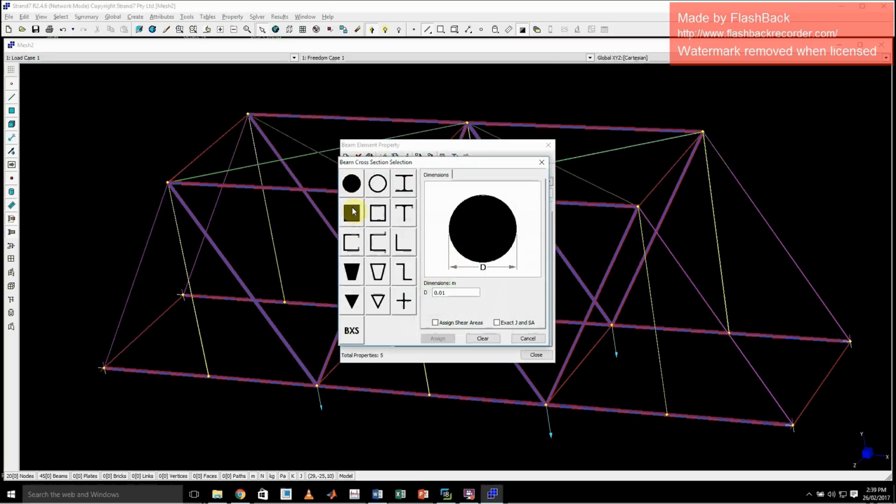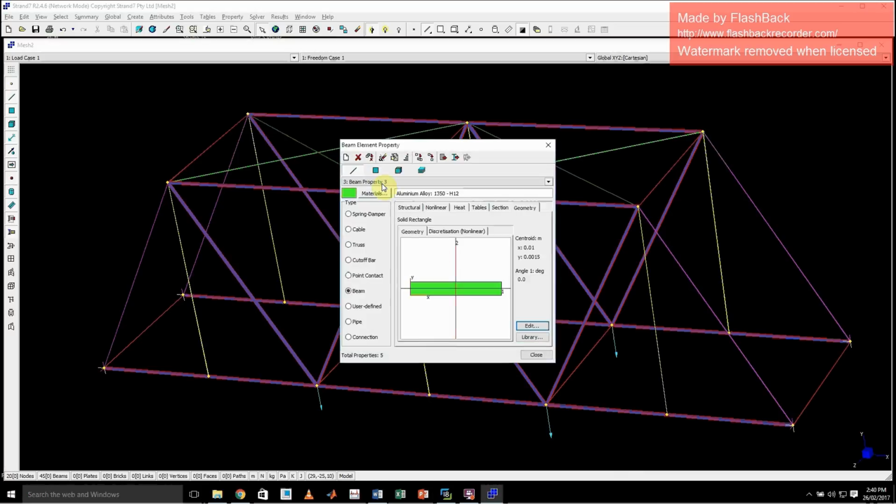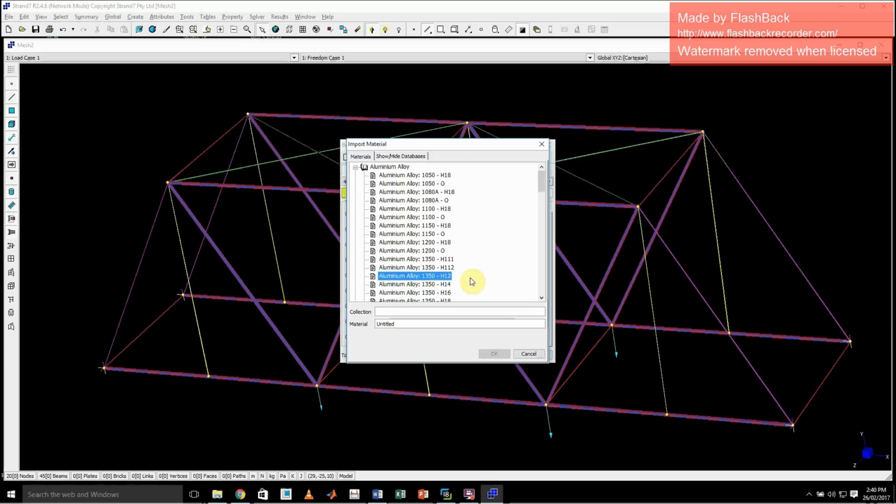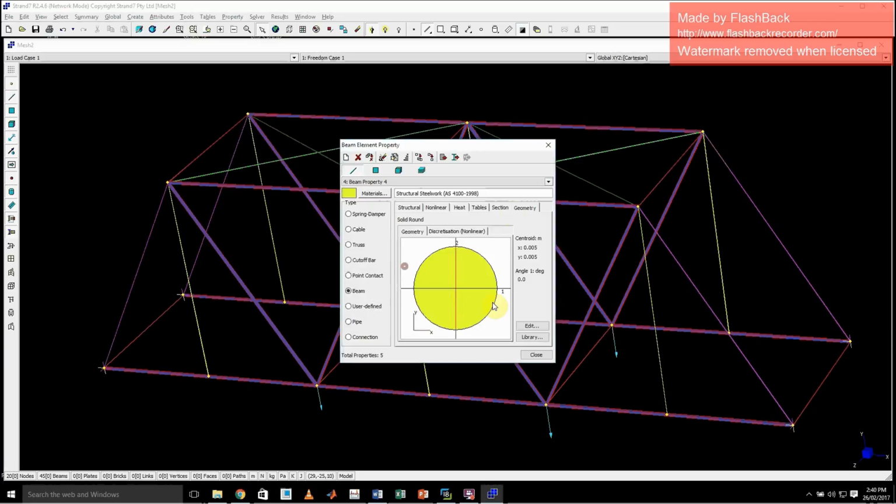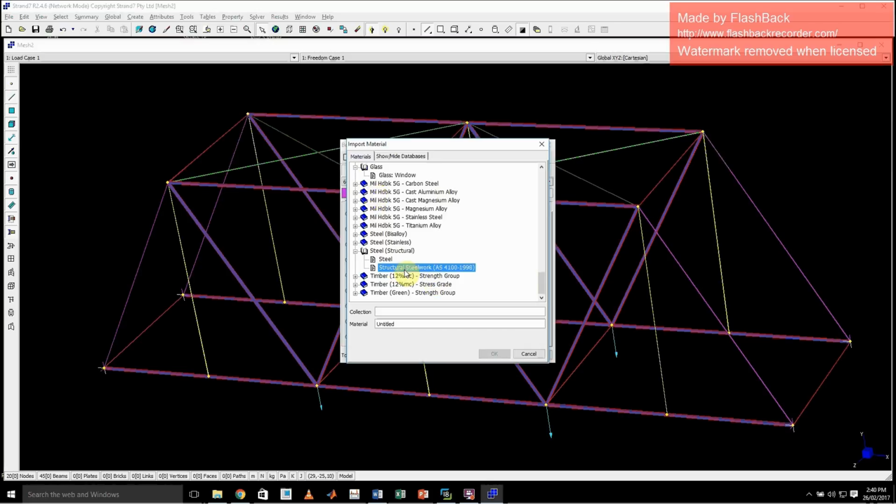You're going to be flat bar, which is 20 by 3, for example. Come through, put all of your properties in for all of your different materials. You can obviously reuse the same ones over and over again if you want, but generally the reason you've got different property types is because you wanted to make them out of different types of members.